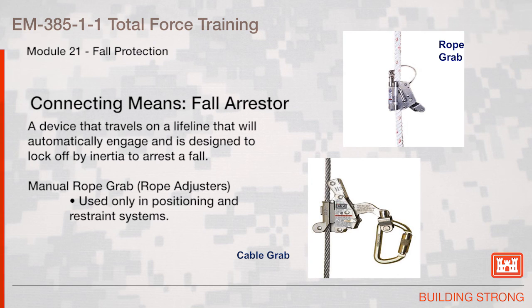Connecting means, fall arrestor. A device that travels on a lifeline that will automatically engage and is designed to lock off by inertia to arrest a fall. Manual rope grab or rope adjusters are used only in positioning and restraint systems.